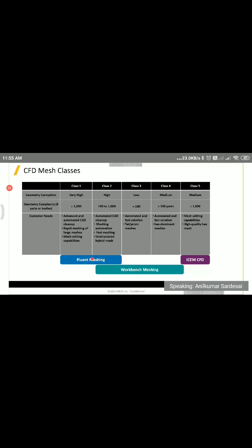You name it, they use this algorithm, Fluent Meshing, to work on their automotive requirements, or for, say, underhood thermal management, external aerodynamics, and so on. They will handle that with our wrapper or fault tolerant meshing algorithms for class 1, class 2 problems, where they might be dealing with hundreds to thousands or more components. Like you have the engine, you have the other parts, so it will definitely go to more than hundreds of different cell zones. So it is a very tedious task to work with such big assemblies and do manual cleanup. And that's why we go with the wrapper technology to generate a good quality surface mesh.